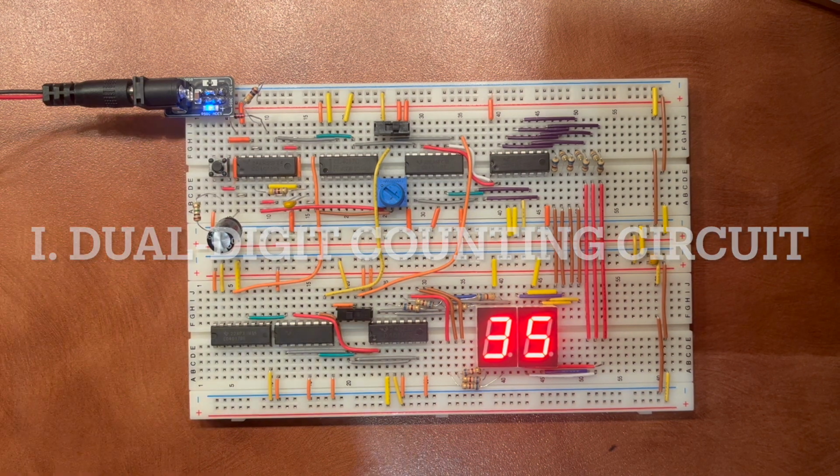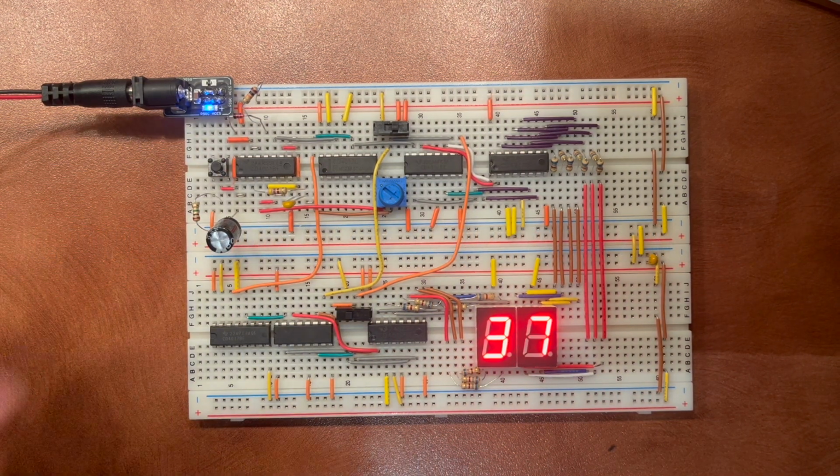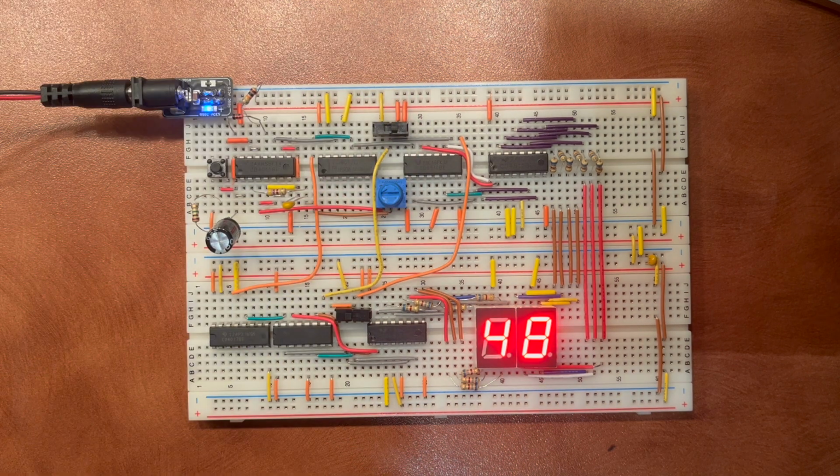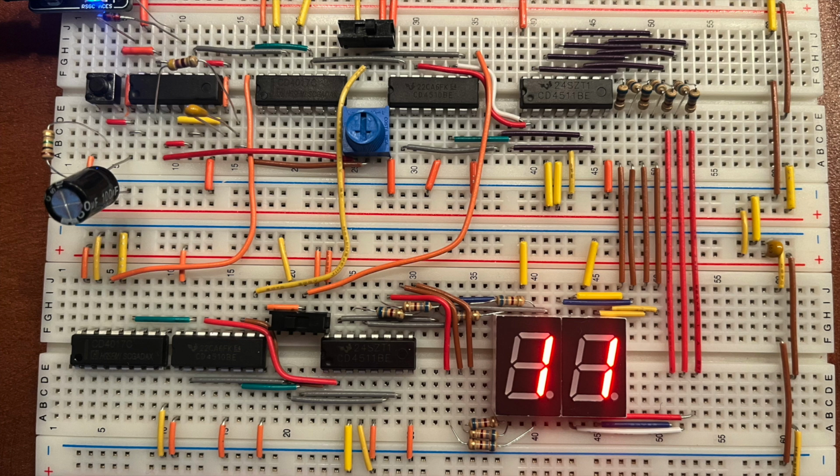The final part of project 1.3 is the dual digit counting circuit. It is made up of two 7-segment displays which can count from 0 to 99. The second digit takes the divide by 10 output and inputs it into another divide by 10 input, making it count 1/100. From there, the steps are repeated, and instead of having two switches for each digit using reset or up/down counting, the second digit functions are wired to the corresponding switch of the first digit, effectively connecting them to work in sync.